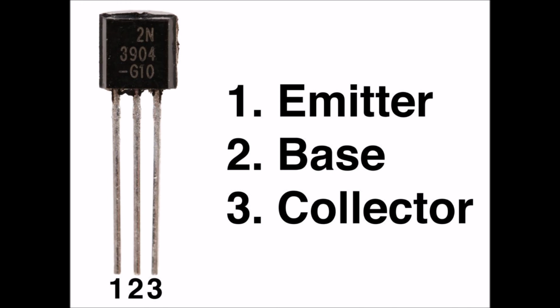The gain bandwidth product for an amplifier is the product of the amplifier's bandwidth and the gain at which the bandwidth is measured. Common emitter circuit. In electronics, a common emitter amplifier is one of three basic single-stage bipolar junction transistor amplifier topologies, typically used as a voltage amplifier.